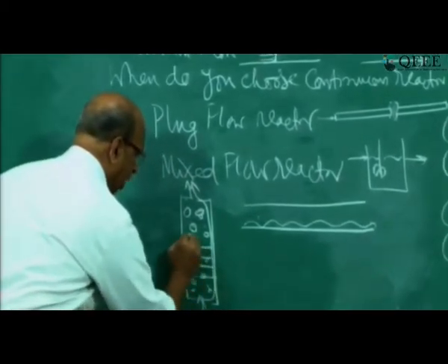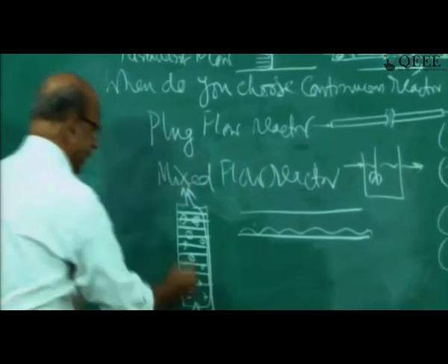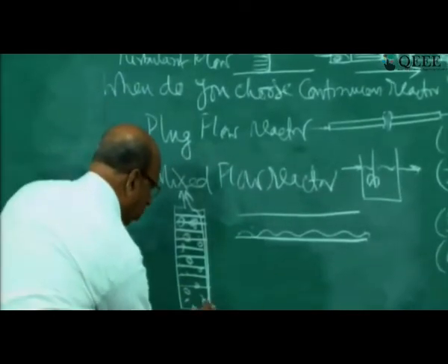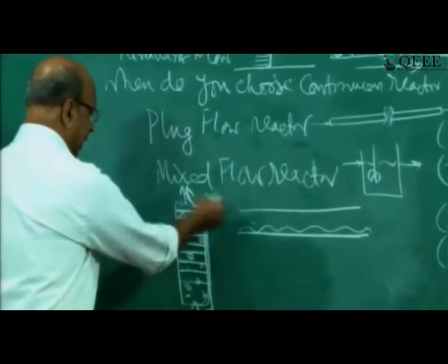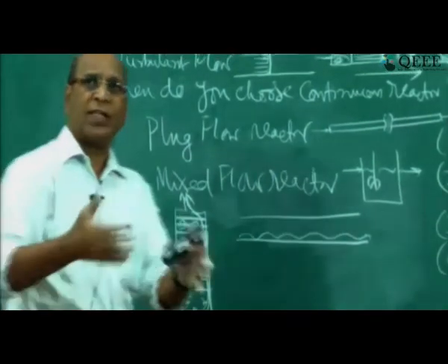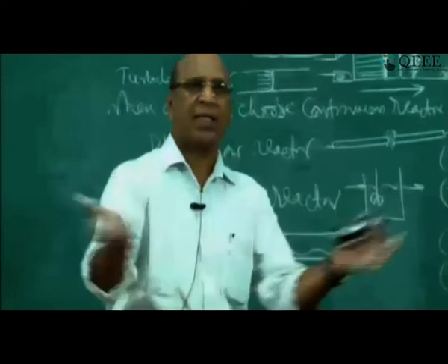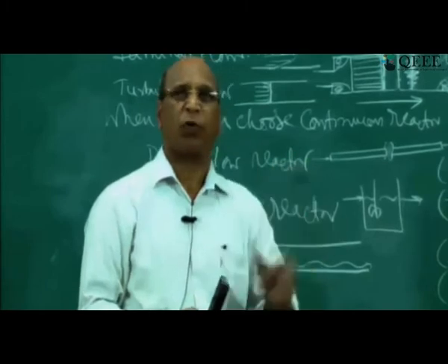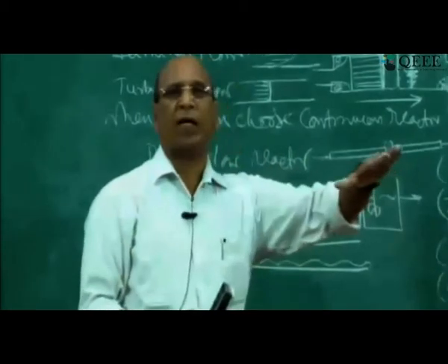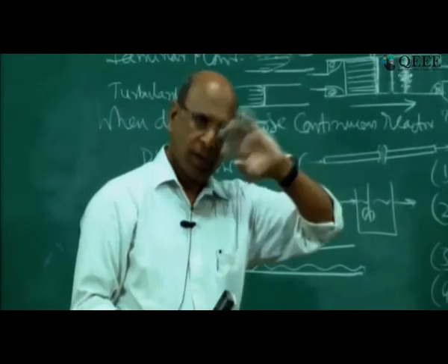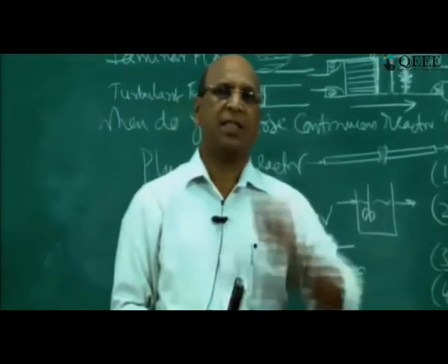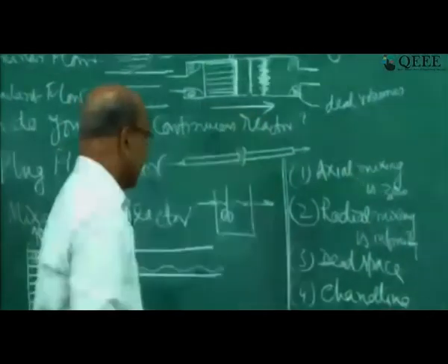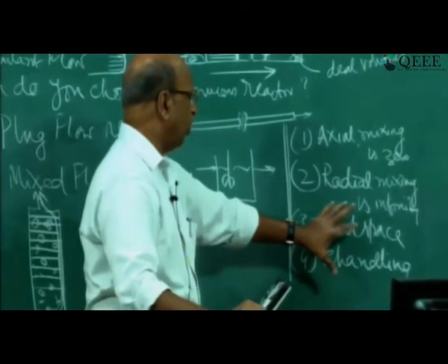This is plug flow. All packed beds are plug flow because you can maintain this kind of velocity profile. But on the other hand, if it is wrongly packed and most of the liquid or gas goes near the wall, because there you have easy flow with no resistance, then it is not an ideal packed bed, not ideal plug flow. All packed beds are plug flow reactors because you can maintain that flat velocity profile, so that each and every particle gets exactly the same residence time. So channeling also is not allowed. These are the things which we should not allow in the plug flow assumption.